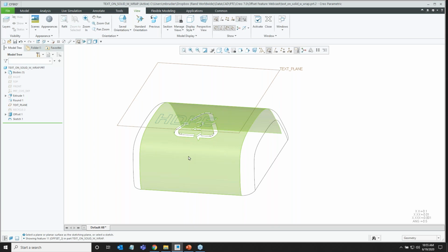Now, projecting something is like taking whatever it is you're projecting, do an imaginary extrude normal to the surface you're projecting normal to, and then look at where that imaginary extrude intersects your surface. That's what the project does. This wrap is more like thinking of the original sketch as a piece of string with a fixed length. You're going to take those pieces of string with fixed lengths, and you're just going to let them fall onto the surface. So in the original sketch, if that was a 1-inch line there, when I wrap it onto this surface, it's still going to be 1 inch long. We saw that when we projected it, it was about 3 inches long. It made it like 3 times longer. So the one step to not distort my letters here is to add this wrapping first.